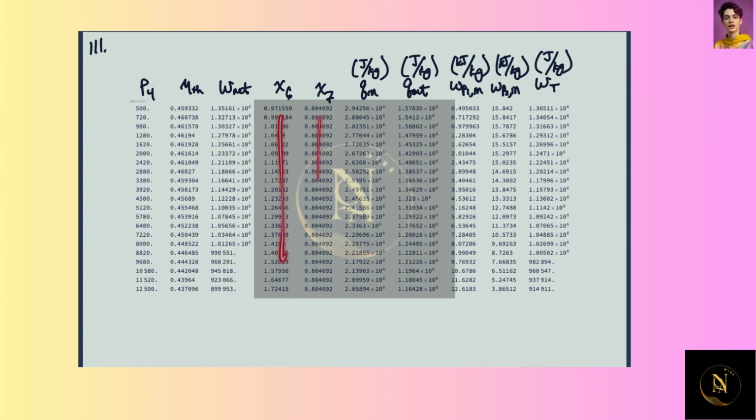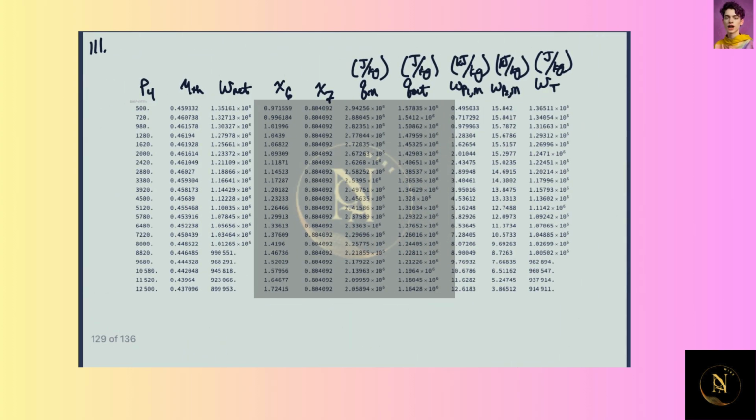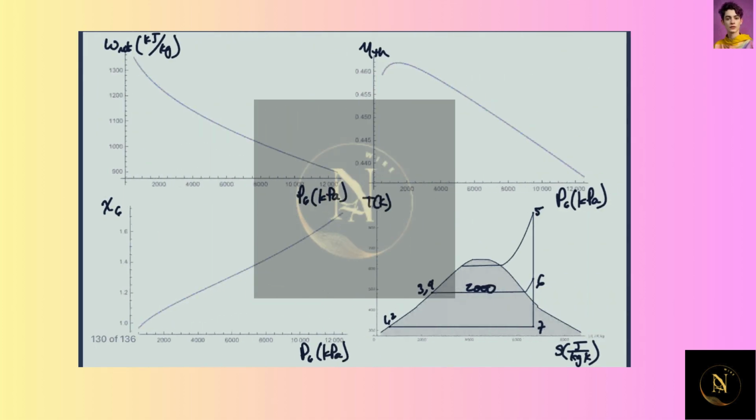I looked at the saturation values here and here. At the bleed, at low pressures we're at two-phase, and at higher pressures we're in supercritical vapor. And at the turbine outlet, it stays constant because this point here isn't changing as we move this line up and down.